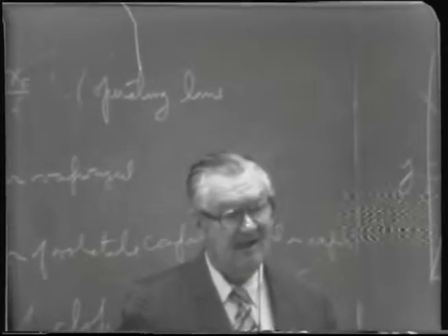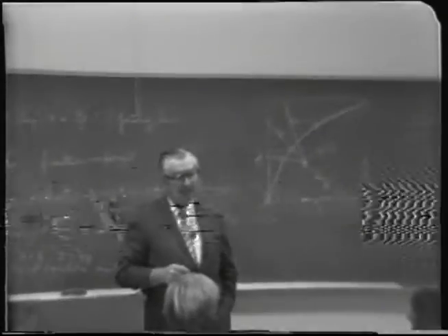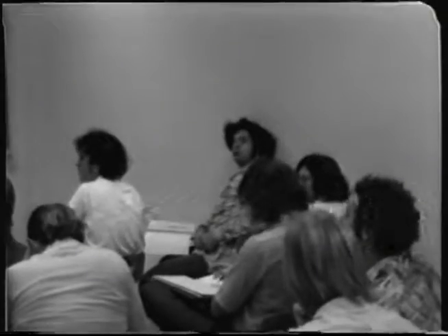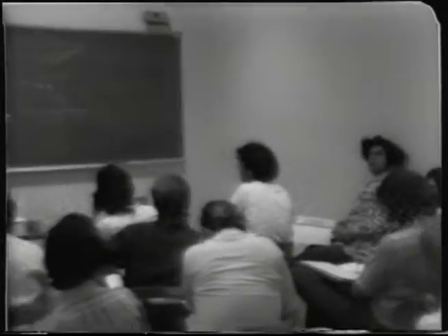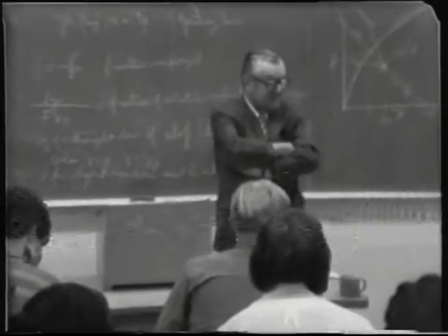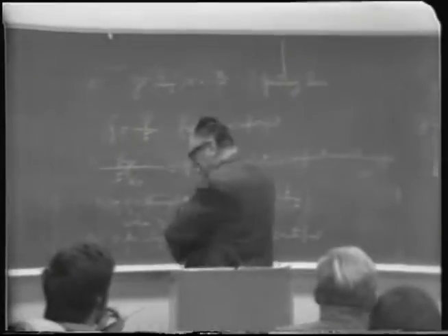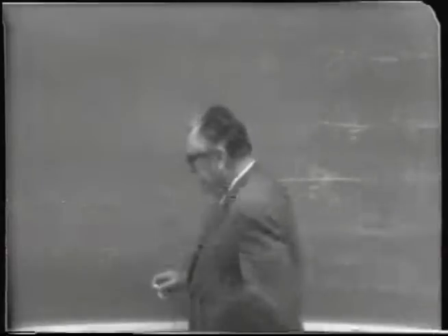Yes? I'm just trying to understand what y stands for. I can see what x sub f is. But y, when you plot over to the left from that upper point, you get y. Now what is y? It would be the concentration of the volatile component we're talking about in the vapor given out. This is given on your handout, but we'll draw another little sketch here.